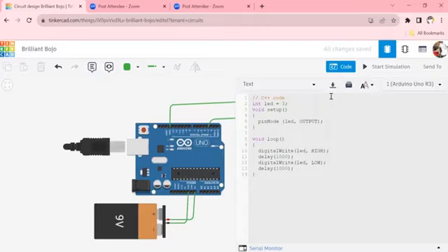Can you hear me? Good. So in your void setup, you also state the pin mode, right? You initialize the pin by adding another pin mode and make sure you take note of these different names. Similarly in your void loop, all you need to do now is repeat the same process we've done here twice for your second LED, right? Is that clear? Yes, please. Okay, good. So that will be a task for you to do.